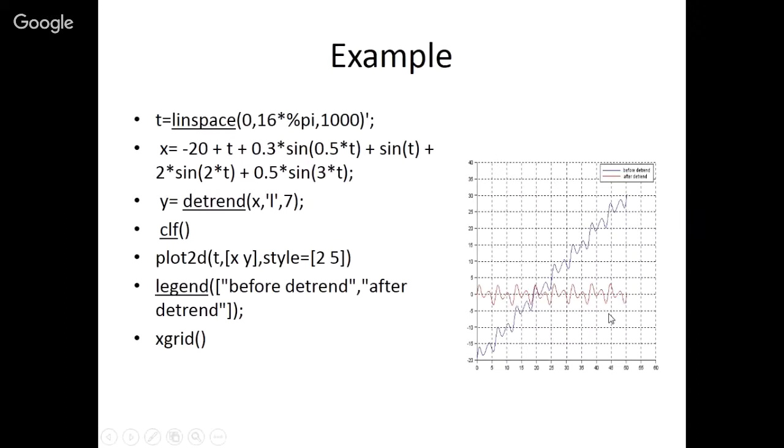So whenever you have a linearity graph but you want to cut it into a constant graph, at that time we use detrend. It may be of any trend, but till today in Scilab, this detrend command cuts out only the linearity or the piecewise linearity graph.